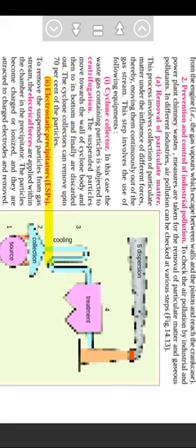2. Electrostatic precipitators, ESPs. To remove the suspended particles from the gas stream, electrical forces are applied in the chamber of the precipitator. The particles become charged or ionized, and they are attracted to charged electrodes and removed. ESPs can remove 99% of the particulate pollutants from the chimney exhaust. ESPs work very efficiently in power plants, paper mills, cement mills, carbon black plants, etc. Sometimes, high resistivity dust may make separation in an ESP difficult. To overcome this difficulty, fabric filters or bag filters are employed. Further, tall chimneys are used for vertical dispersion of air pollutants.